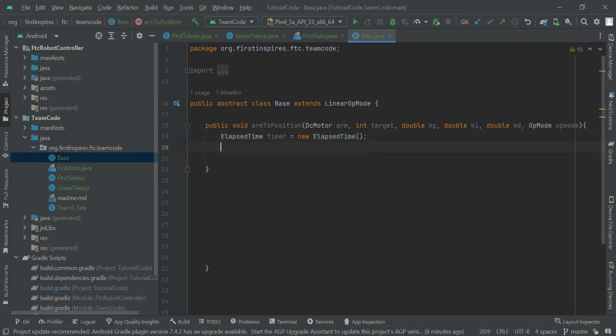Now, we're going to set a margin of error. For example, in this case, I'm reading ticks. So if I give it a target position, within how many ticks do I want to be? You don't want to set this to 0, because if you do, the robot will oscillate around that point and won't stop the PID loop until it gets exactly that position. So you're going to get a very wobbly movement. I like to set this to usually around 3 to 5 ticks. So I'll just make it 3 for now.